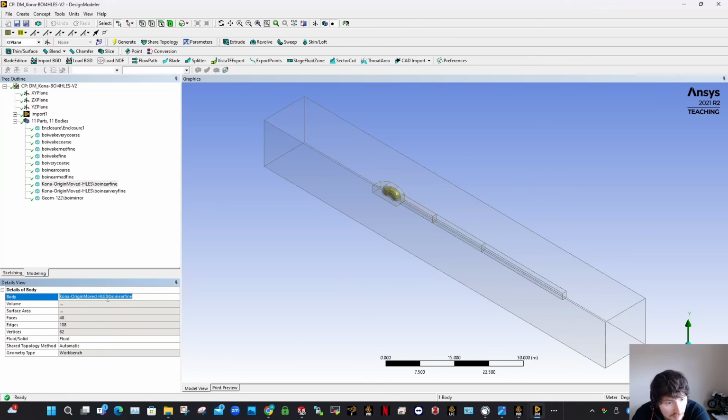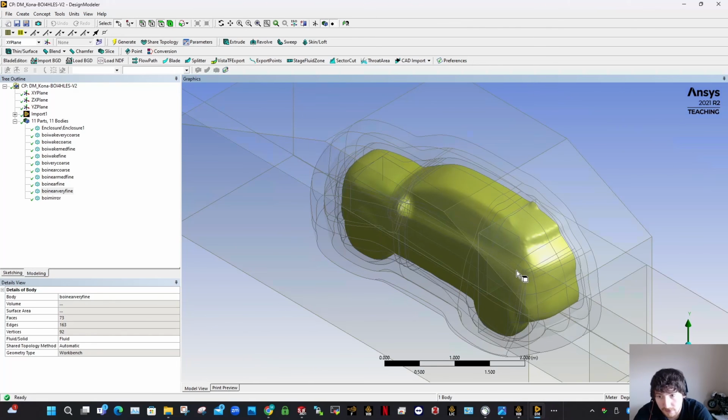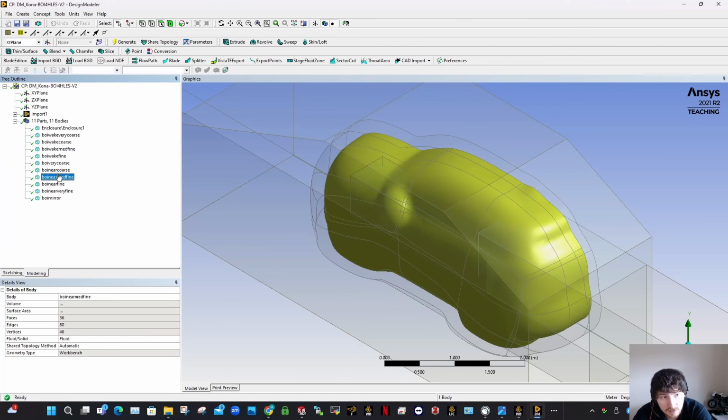Grand, so when all this is done, I don't know if I'll add on the bit of me pushing this through the mesher, but I'll just talk about mesh sizes now, just so it covers things up. So that's up to you. You decide what you put these on depending on your computational resources. I know that very fine layer near the vehicle, that's 5 millimeters for me. I'll zoom in here. That very fine layer there is 5 millimeters. The one outside of it then is 10 millimeters. This then is 18 millimeters.